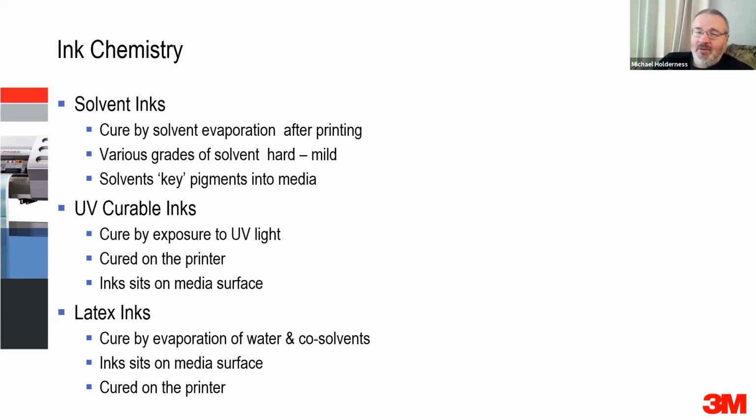Now I'm going to get a little bit technical here. For you guys with UV printers, you've got a choice of a couple of different curing methods. You've got a choice of curing on the leading lamp and curing on the trailing lamp. Those of you with UV printers should understand what I'm talking about. What we find is that for a nice, smoother surface, we tend to turn on the leading lamp.